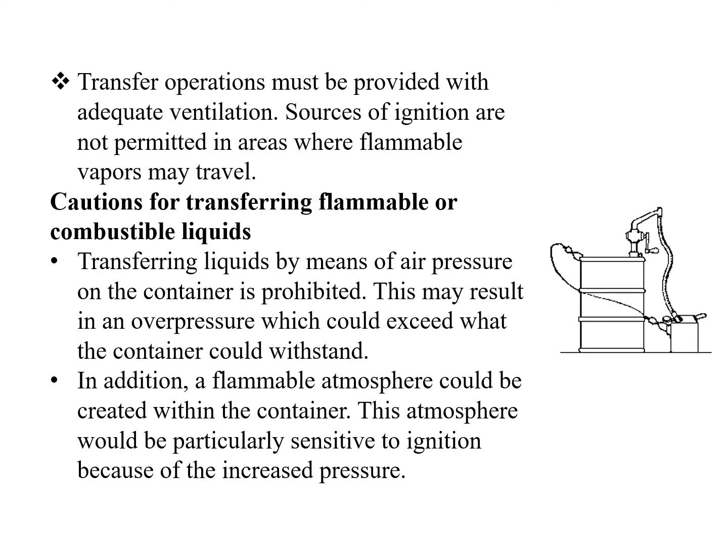During transfer of different flammable liquids, it's better to select a place with adequate ventilation, and of course there should be no source of ignition, so that nothing catches fire during the transfer of flammable liquids, because there will be flammable vapors available, and they can catch fire. And there are certain cautions you can also take while transferring flammable liquids or any combustible liquids.